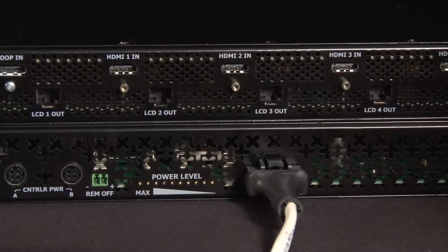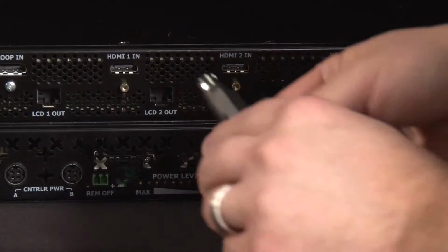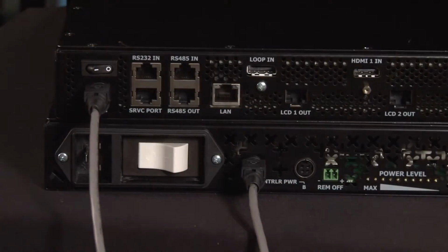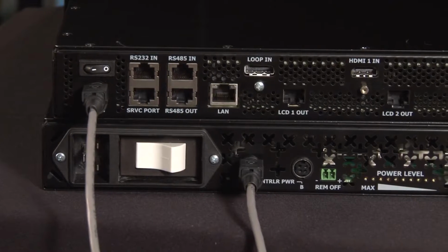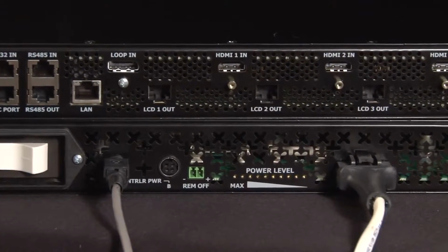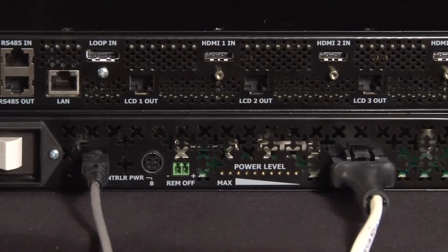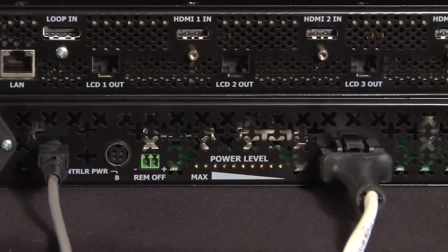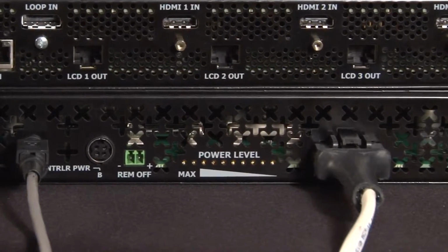Connect the primary power cable from the A1 display to the power supply module. The quad controller is also powered by the power supply module, so connect the power supply cable to the quad controller. The power supply module is capable of driving 2 quads when powering more than 4 panels. During the installation, you can use the power meter located on the back of the power supply module to verify that you have correctly cabled the video wall.